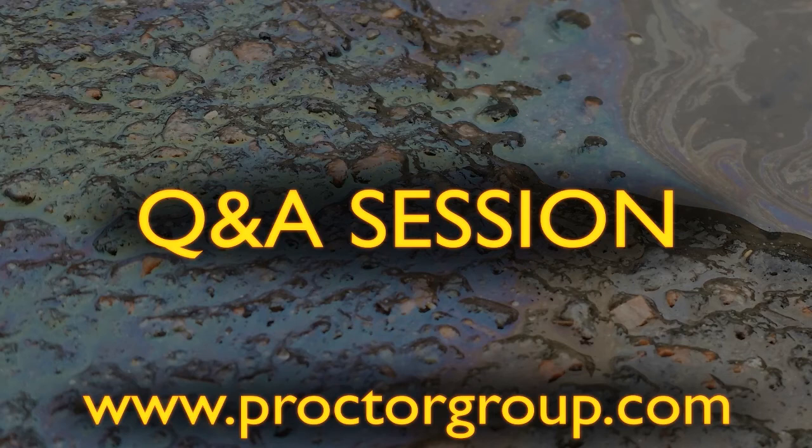Okay. And last question, which just popped in on email, how can you ensure good installation? The guidance documents that are out there at the moment state that installers should be certified to CQA level 2 for installation of a gas membrane. However, with the recommendations in CIRIA 735, it states that all gas membrane installations should be independently inspected and verified. And assuming that that's done correctly, this should eliminate many poor installations that may have occurred in the past.